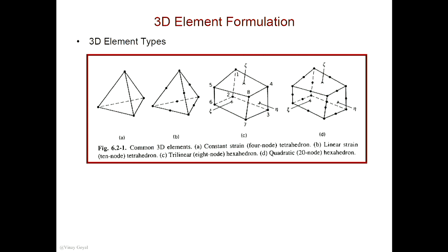So the 3D element types, the common element types are the tetrahedron, which is going to have a constant strain throughout that element. The second order tetrahedron, you also have the cube, hexahedral, and then the second order hexahedral. There's two of them in Abaqus. So in Abaqus, C3D4, C3D10, C3D8, C3D20, and they also have a version called C3D27, okay, which is computationally expensive.